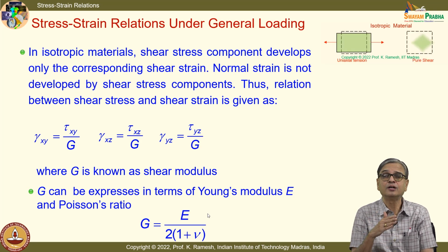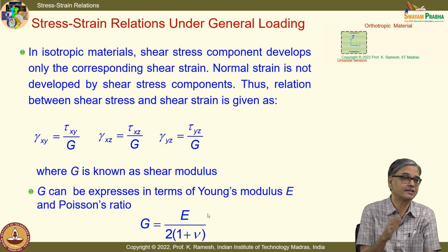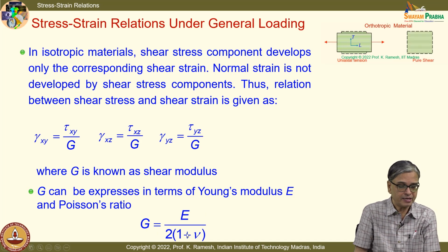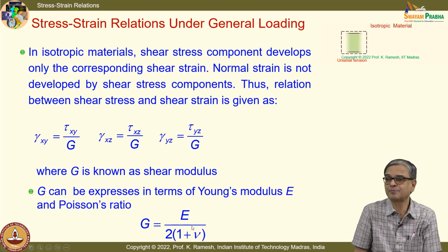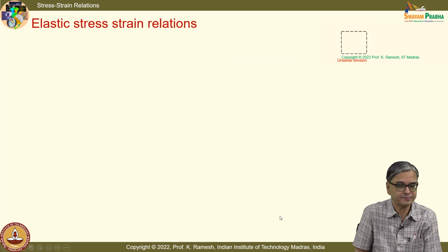You can also mathematically prove it from your background of Mohr circle, looking at strain and stress and finding out how they are related. And from this you find, with nu around 0.3, that your rigidity modulus, this is also known as modulus of rigidity, and you call this shear modulus. There are multiple names, and this is smaller than the Young's modulus. And let us summarize these relations.